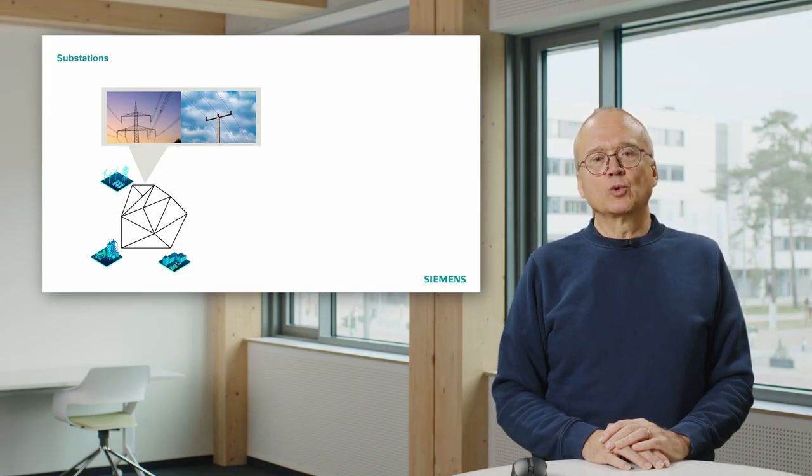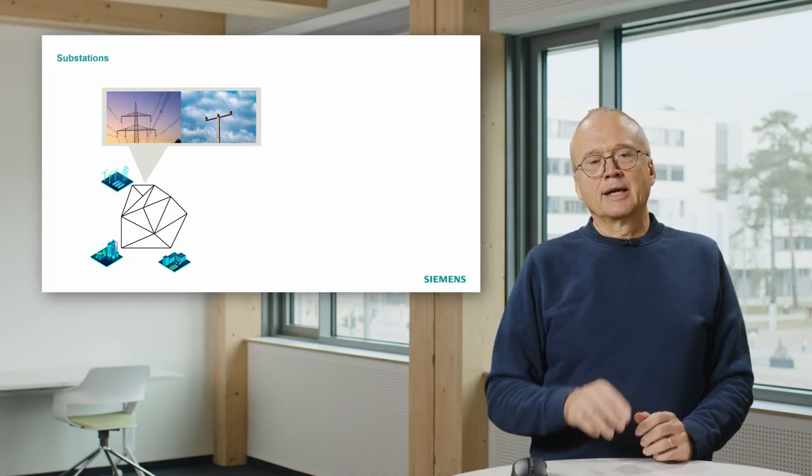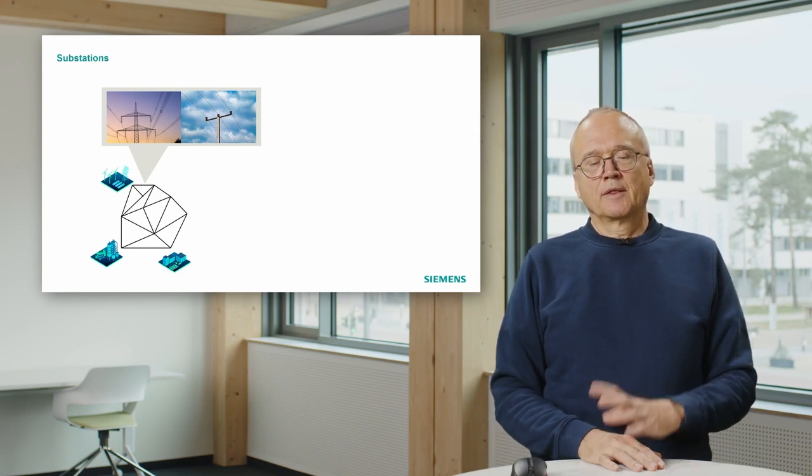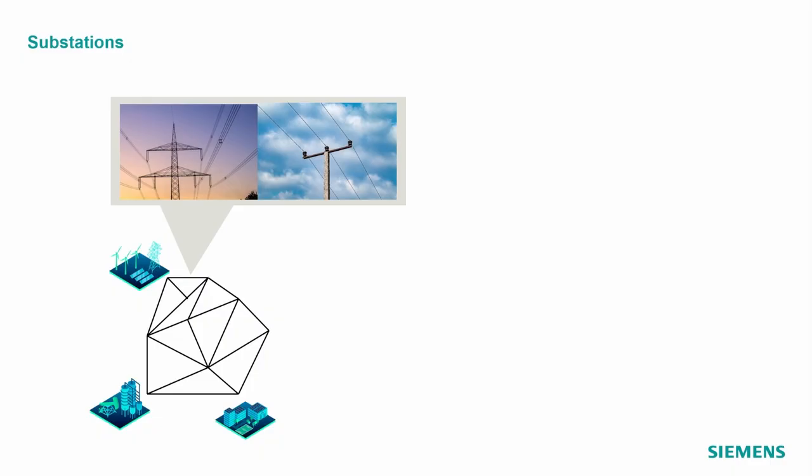We always use three-phase systems. That means one line in this so-called single line diagram is equivalent to 3 lines on this tower. On the tower on the left-hand side, for instance, you see 2 systems, 2 times the 3 phases.